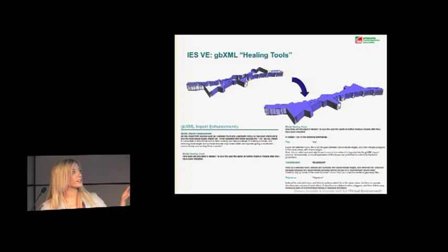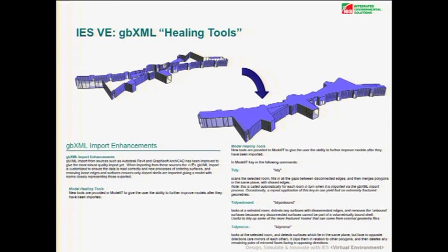What we've tried to do is fill in those holes for you. We've made a decision that if the hole is smaller than 1 square meter, then it's going to become an opaque surface, a wall or roof. And if it's vertical, it will fill in as a window if it's larger than that.